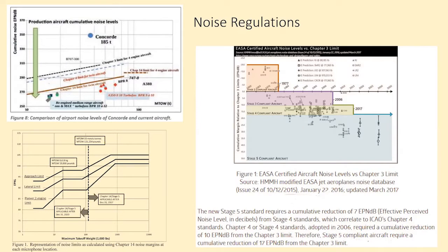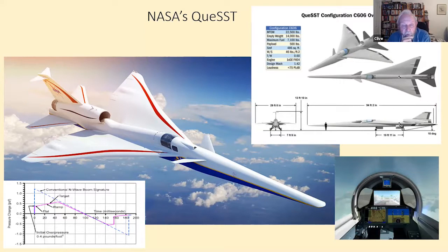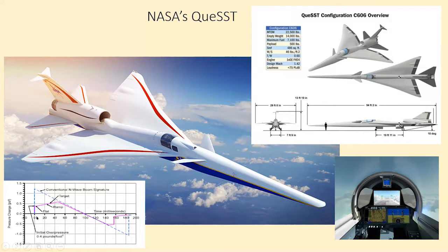I think there's at least one aeroplane, what we're talking about, which might be in that state. Right, look into the future a little bit. Sonic boom, we have NASA's Quest program, which is progressing well. They are, as I understand it, trying to reduce the noise nuisance by modifying the characteristics of the sonic boom to spread the rise time over a longer time, and in fact to reduce it. As I said earlier, I think they will also look at that secondary boom noise.